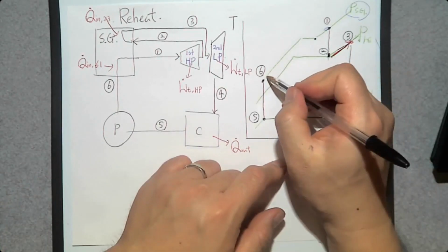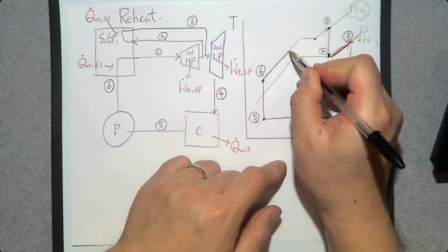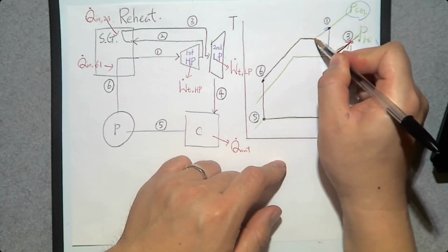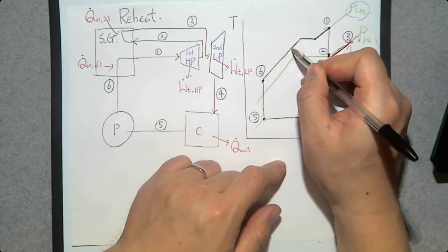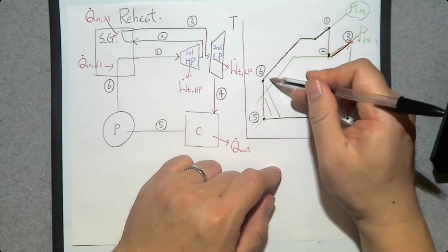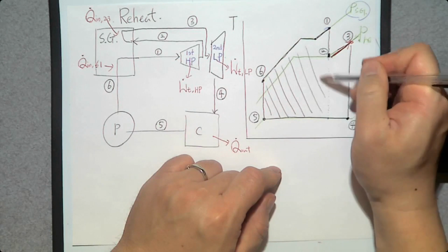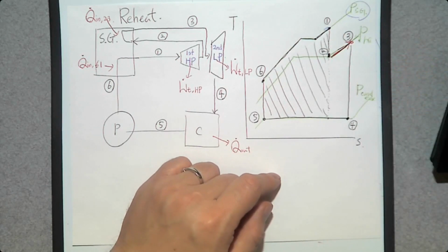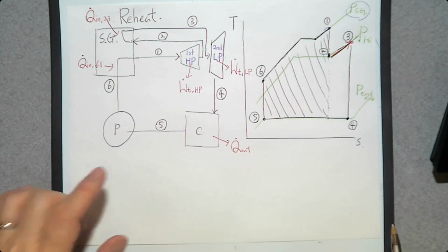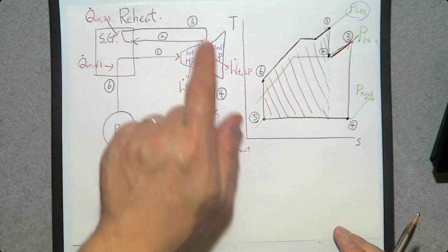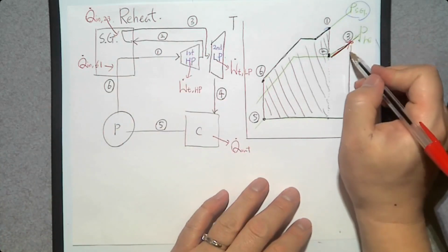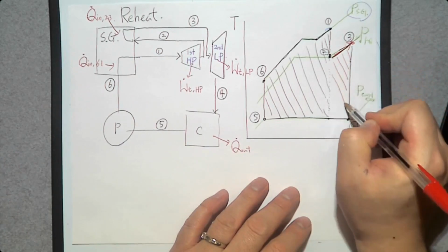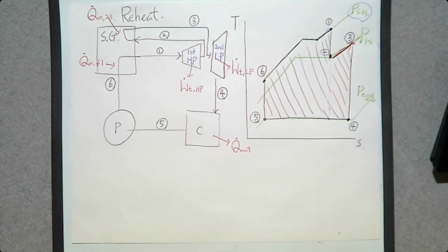So its temperature goes up when pressure P remains constant. In other words, on this green line. So this is the typical power you can produce by the standard Rankine cycle. But with this reheating process, you can add this much power. Okay?